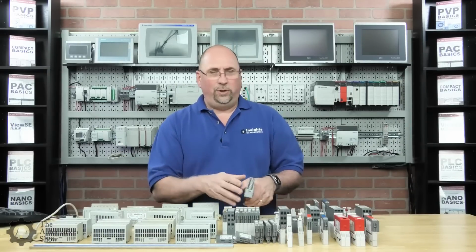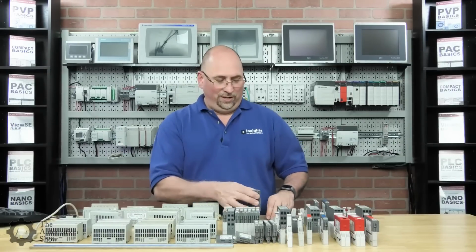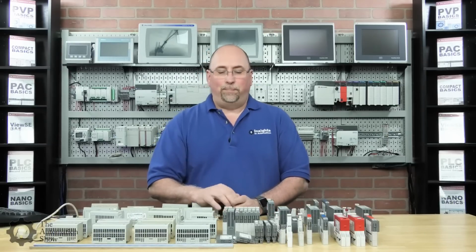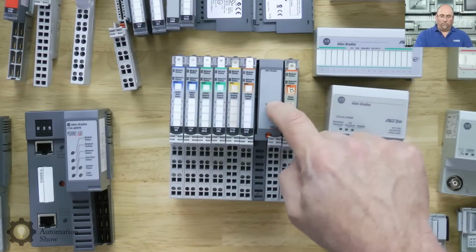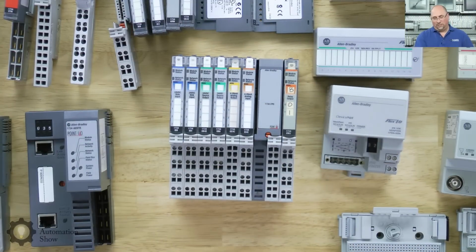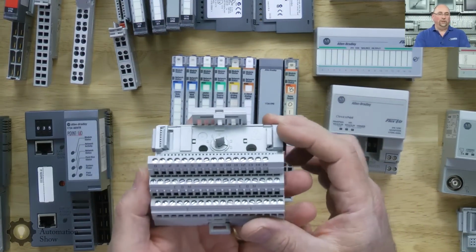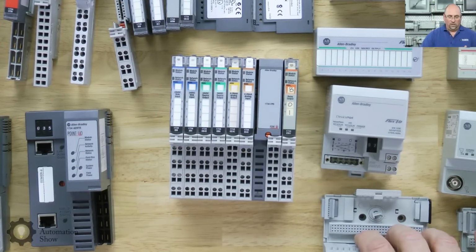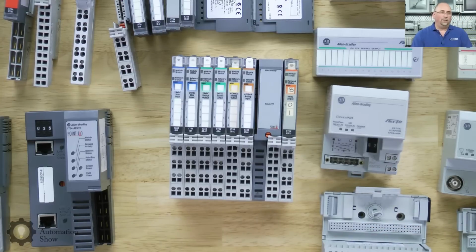So keep that in mind. Point I/O can support up to 63 modules per drop, depending on the device. But you have to take into account the FPDs and the EP24DC. So it's not as simple as when everything was isolated with the FlexIO and every terminal base was its own island, unless you daisy chained them together, which a lot of people did if they were the same voltage. But in any case, that's a huge difference between the two.